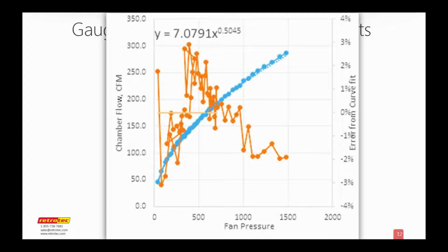So I took a duct blaster and I lay it on its back so it's blowing into the floor, so its flow is obviously 0. And I turned it up to full speed and I measured the pressure, and sure enough the pressure was 2 inches. And the flow reading was 850 CFM. Now, clearly, there was no flow going through the fan at all, but what's happening is the flow was going around and around and around a circle, just like a big donut, and passing the sensor each time it went by, but the actual flow was 0 through the system. So this is something that can happen if you have too much back pressure and go outside the specifications of the device you're using.